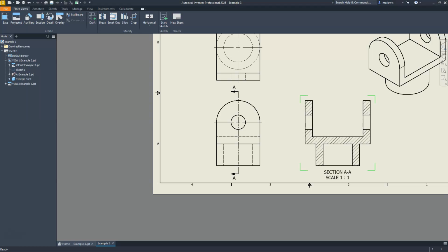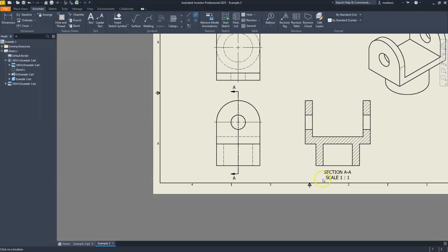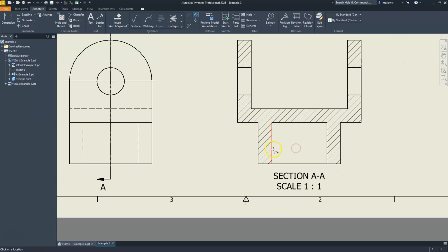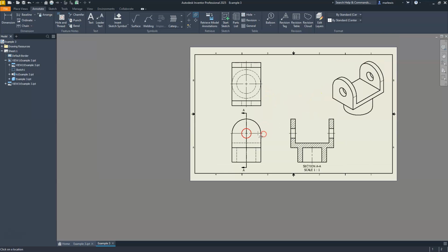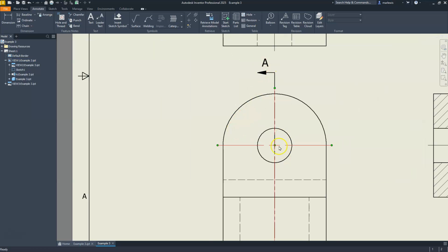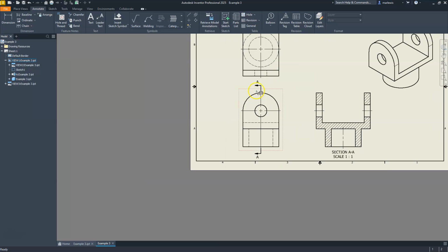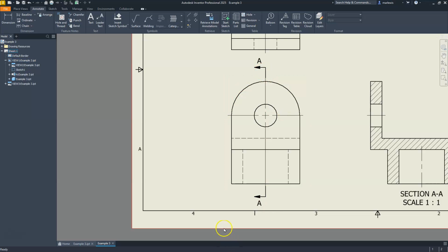Okay. All right, let's put some center lines on that. So I'll go back to the annotation here, do the bisecting, and I'll place them on here, here, and one more here. Okay, so that's all of the center marks I need. Another thing is that I can hide this whole entire line here. I'm just going to select it here, do a right click on it, and then I'll uncheck the entire line. And now it's going to give me just the top and the bottom portion.